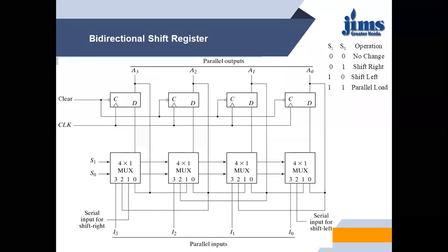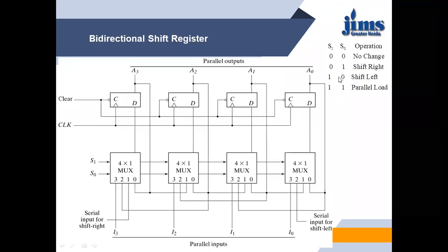So whenever the select lines are 0, 1 and we give an active clock to all the flip-flops, the data is shifted right, serial in.